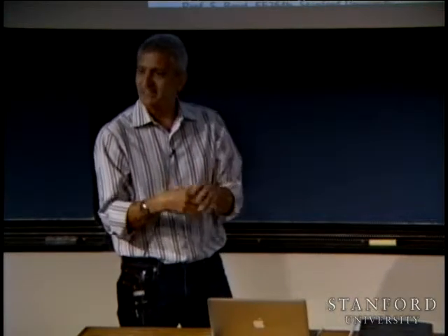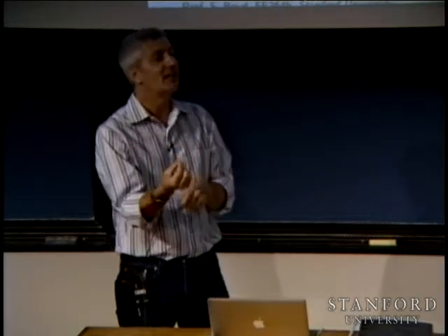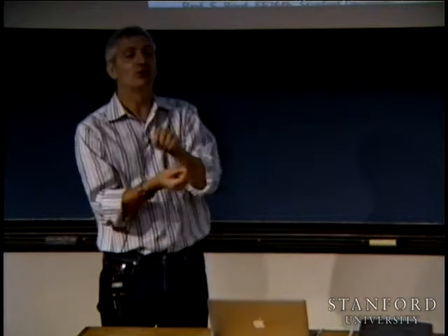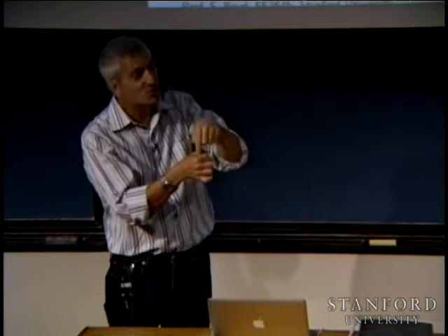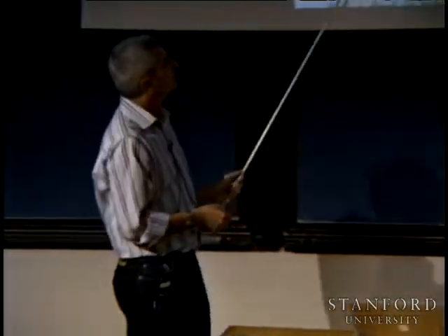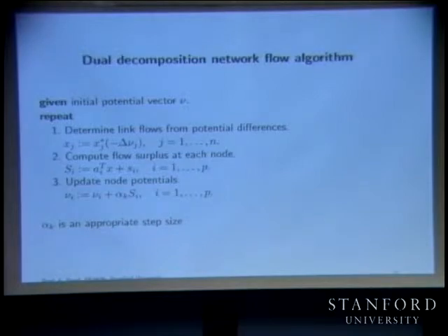If that potential goes up, everybody flowing into that node is going to flow a little less in, because the voltage just went up. And by the way, the outflows from that node are also going to increase a little bit, because if you pull the voltage on a node up a little bit, the outflows increase. But if the inflows go down a little and the outflows go up a little, then if that node was oversubscribed before, with too much net current, that's actually a correcting move. And the point is that these are embarrassingly simple to write down.